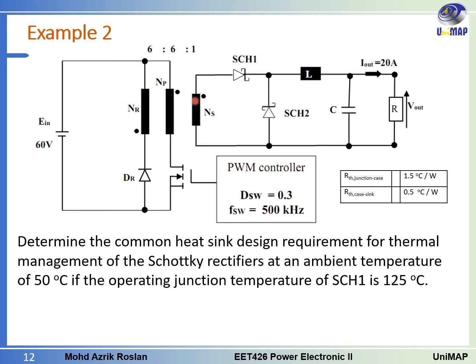So you have to know how many components are involved when you want to design the heatsink. Sometimes there will be maybe 2 diodes and 2 MOSFETs, so you have to base your calculation on those 4 components. For any circuit given in the question, you have to be really careful about how many components you should design the heatsink for.